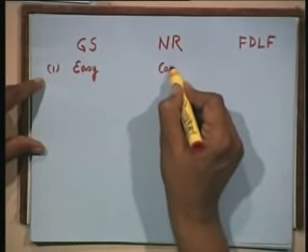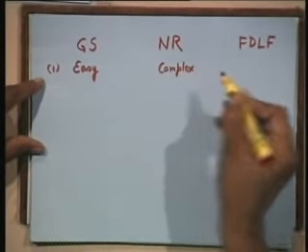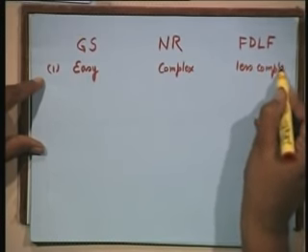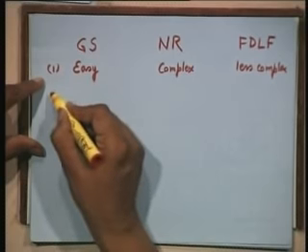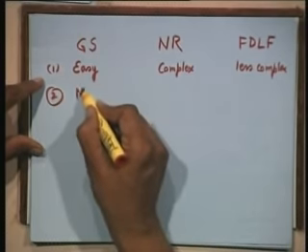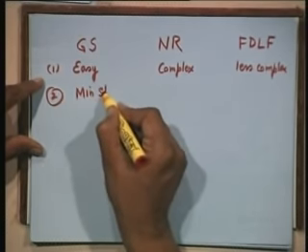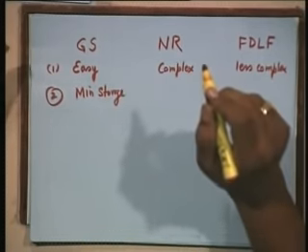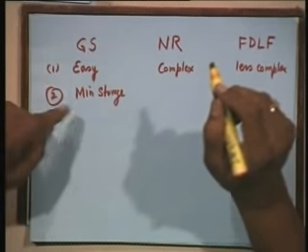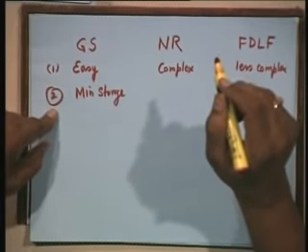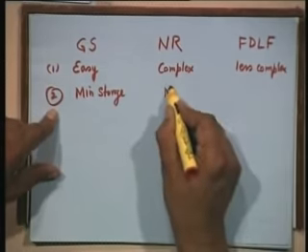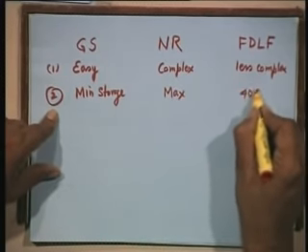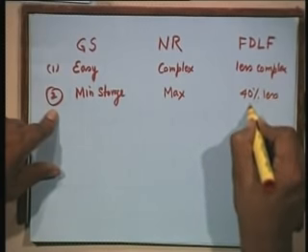Newton-Raphson method is complex. This is slightly less complex because only one inversion is involved. Minimum storage requirement is in Gauss-Seidel. In fact, there is no other method which can have lower than this as a storage requirement. Here is a maximum storage. This is 40% less than NR.